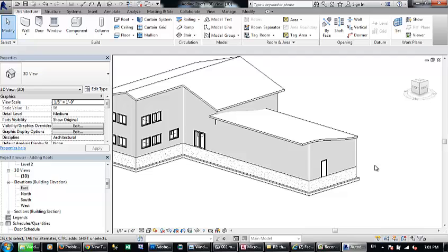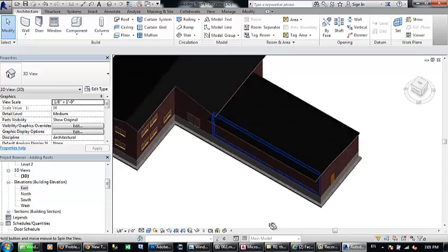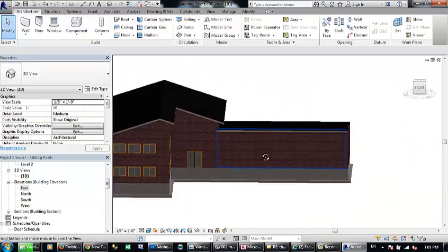In the last chapter you will learn how to give a material for the roofs, for the walls, for everything. So you can tweak the material here very easily. But right now, if you want to see the material, you click realistic, switch to the realistic mode. So you can get an idea what is the default material of the roof. So this is the default material. It doesn't have any texture.